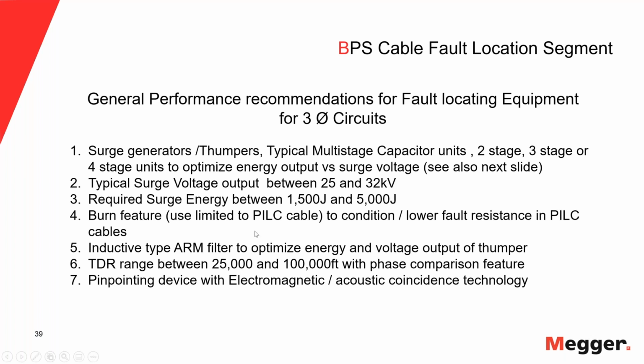Okay, burn feature. Many people swear by burning faults, and a little bit of caution needs to be applied, because if I burn solid dielectric cables, I normally shoot myself in the foot. What happens when you burn a solid dielectric cable is you set the whole insulation material on fire, which means it smokes away.